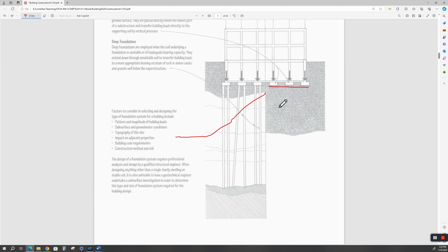And so you have to come down and go through all this garbage with something that'll support the building load. And in this case, it looks like they used cast-in-place piles. So you dig out all this nasty dirt, come in with some good stuff and compact it really good, put in these footings, but before the footings, you'd come down with drilled piers and then cast the footings on them, okay? So they extend down through unsuitable soil. Don't be surprised if that happens.